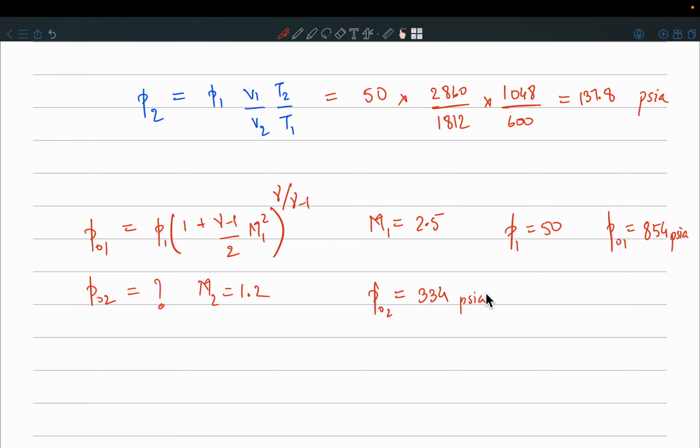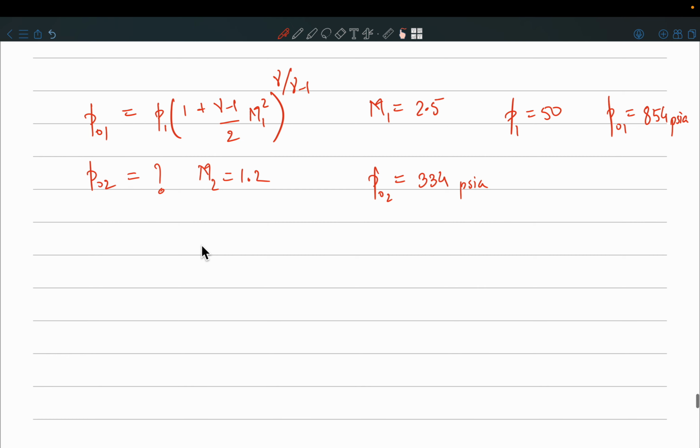Okay. So now what you can do is you can simply use that formula. P naught 2 by P naught 1 is equal to e to the power of minus delta S by R, and R is your R gas. If you just plug in the values, you can find delta S, and P naught 2 by P naught 1 is less than 1, because P naught 2 is lesser than P naught 1. So when you take the logarithm, the negative sign gets cancelled, and delta S value will be, in FPS units, 0.058, but depending on whatever units you are using.